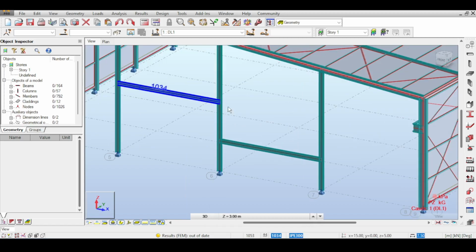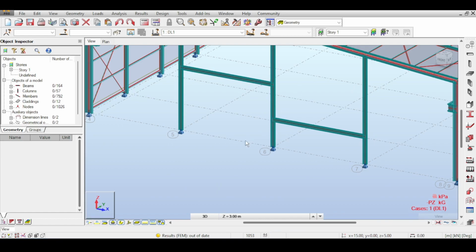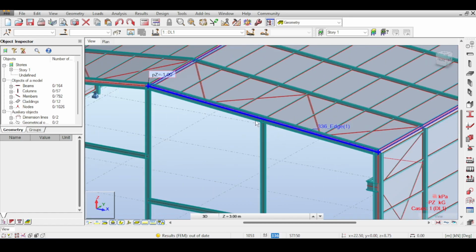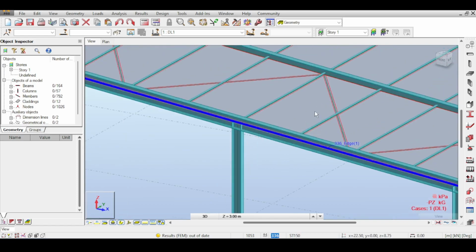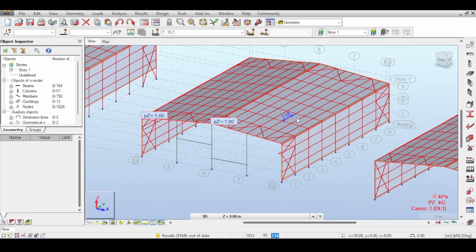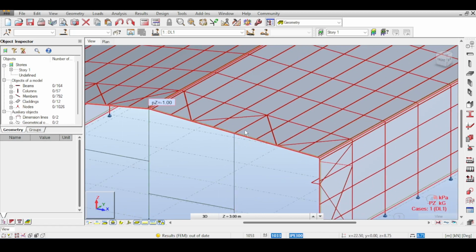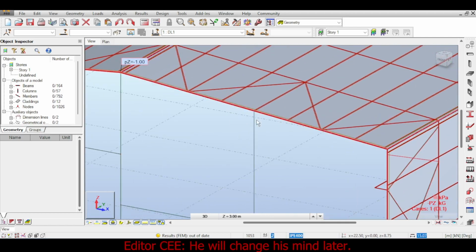Of course, this is a moment resisting frame. I'm assuming that this is a moment resisting frame, so I'm not going to brace it. However, this might need lateral bracing. Oh, I need to brace it, right? I have an idea. Follow me with this. It's going to be cool if it works. Wow. Okay. The idea is that I want those to be also, because they are going to be released, I will not connect them to the portal frames in their axial direction,